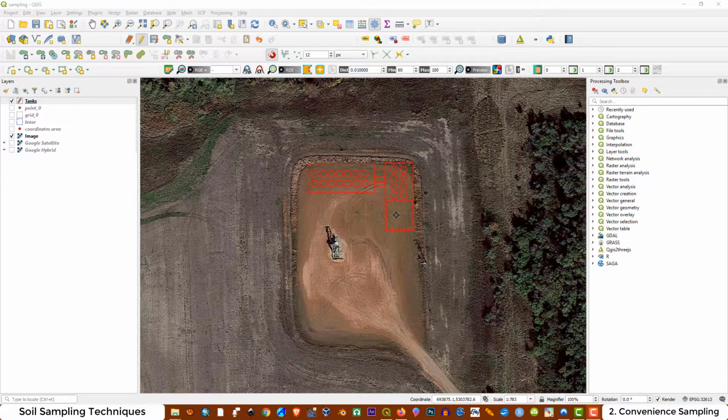They were above ground tanks that stored hydrocarbons. Then the tank area was removed, and now we want to know if there are any impacted soils related to the hydrocarbons or even to metals associated with the petroleum activity in this area, not just with the tanks, but also with the building facilities and the potential storage areas.